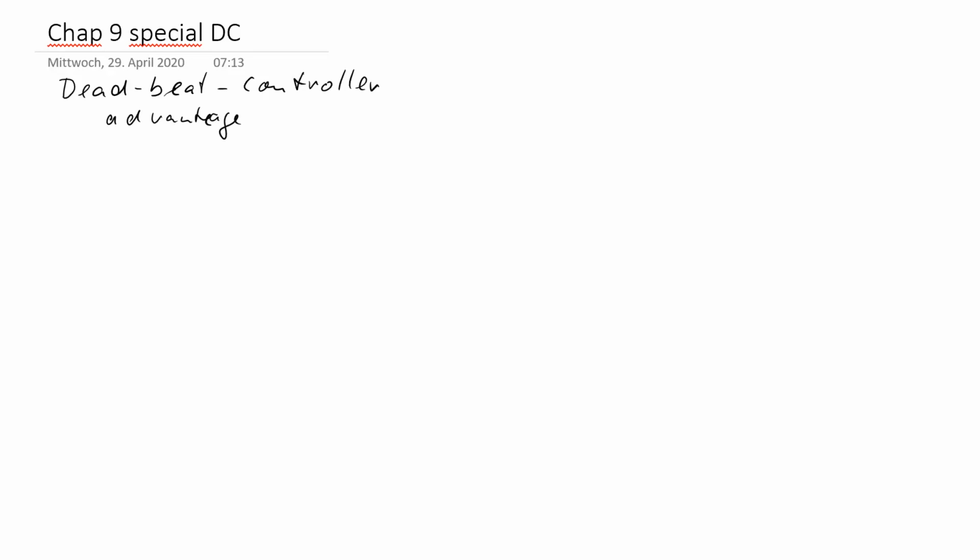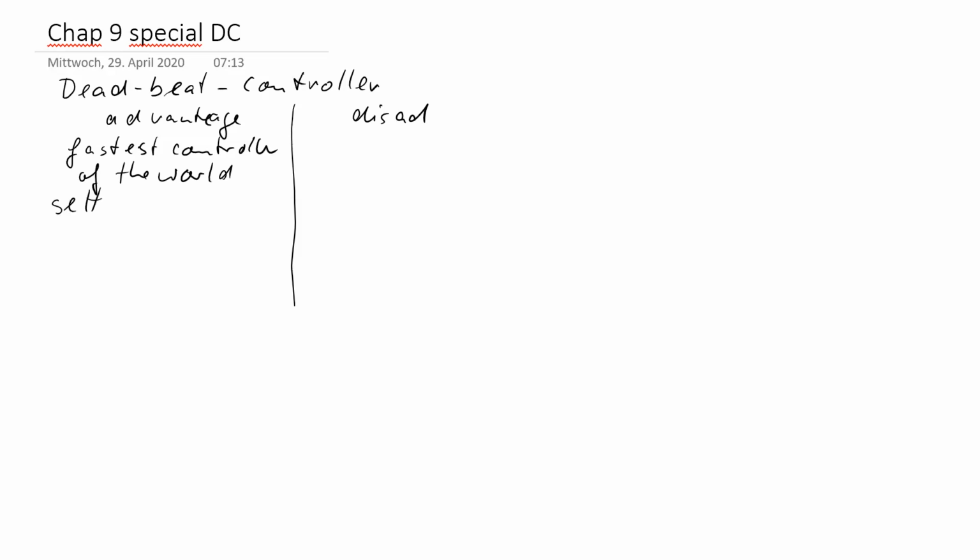Advantage. Disadvantage. A list to show you what happens. It is the fastest controller of the world. Why is this the fastest? Because the settling time in the reference step response is m times the sampling time, if m is the degree of the process.